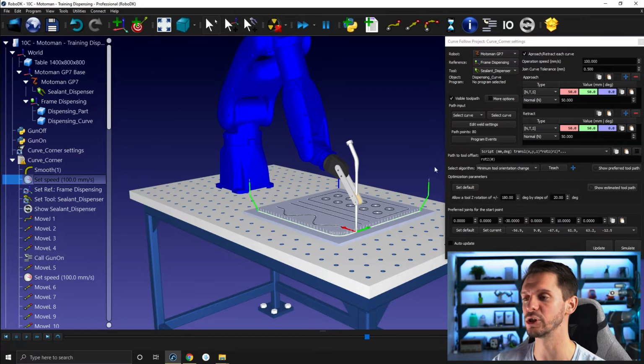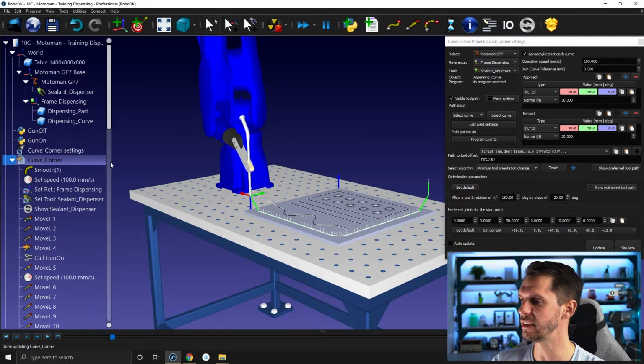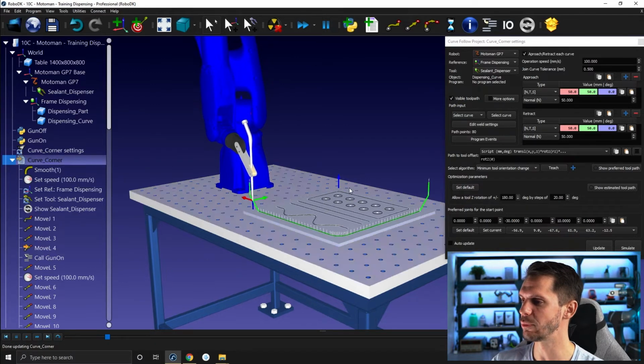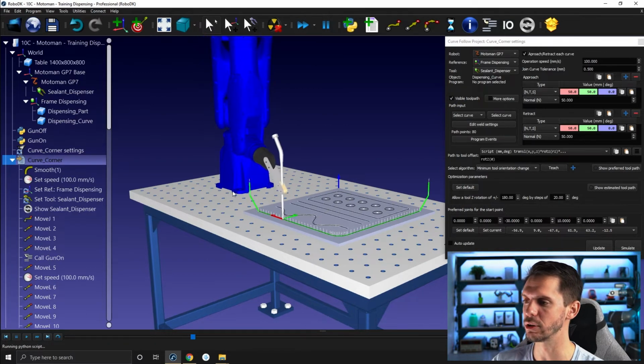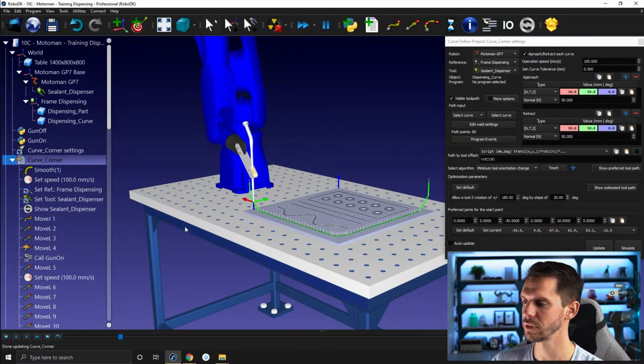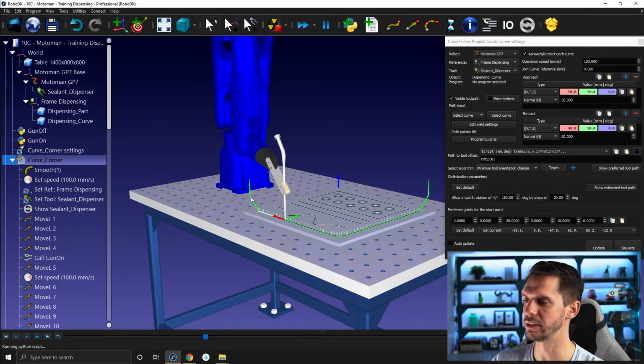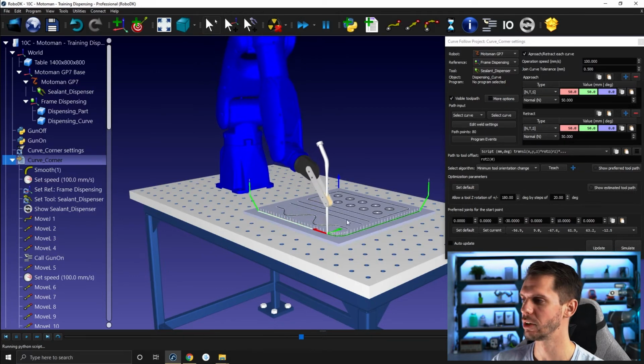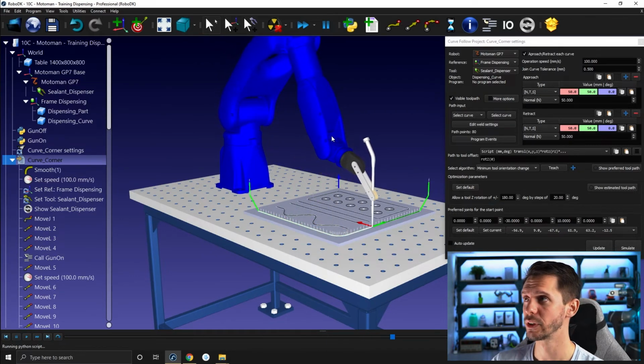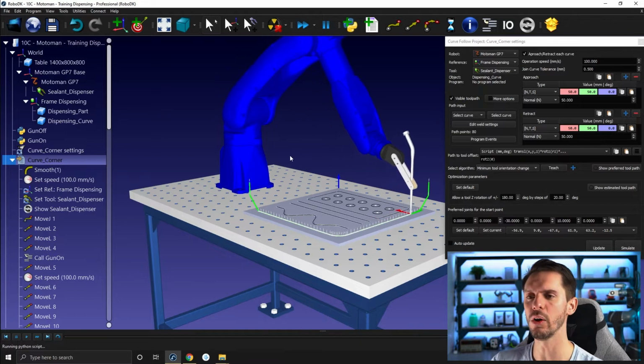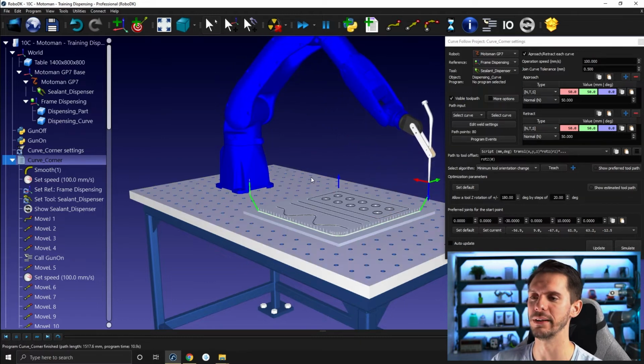Now I'm concentrating just on how speed works within RoboDK. So if I do that here, now we'll have 180 degrees per second to go reach that point here. And then I will have the rest of the program run at 100 millimeters per second for all of those sections. So that's cool. Now let's talk about rounding.